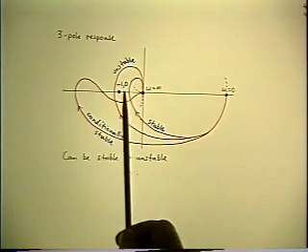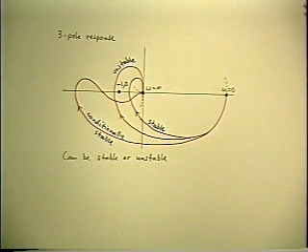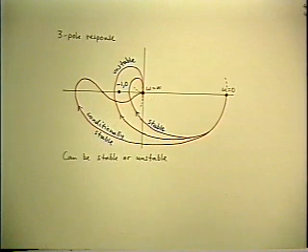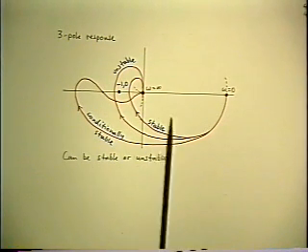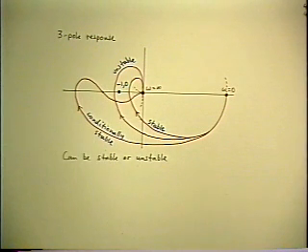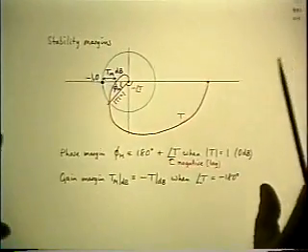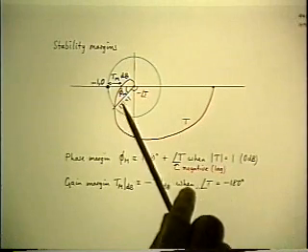So you see, there's all sorts of hazards in a conditionally stable system, mostly to do with abnormal conditions. But to try to anticipate all those possibilities is a pretty tough thing to do. So the basic conclusion is, don't design a conditionally stable system unless you really have to. Stay away from it. So let's go on to the next point, which is, now we want to have a